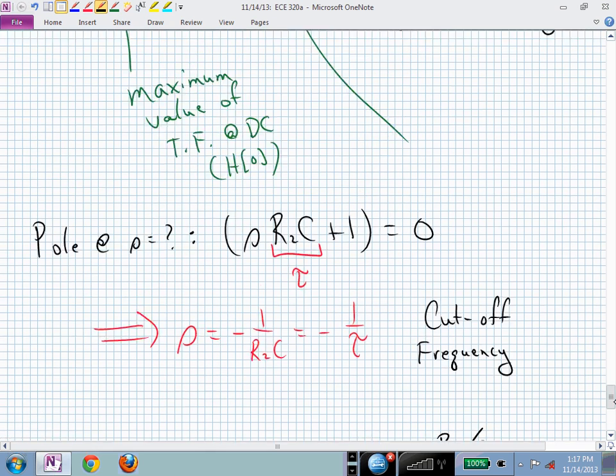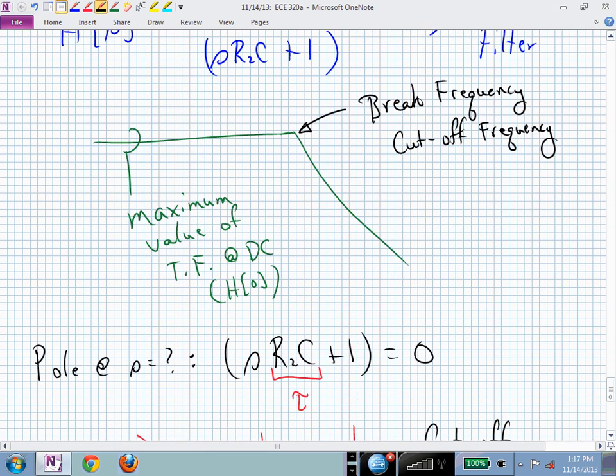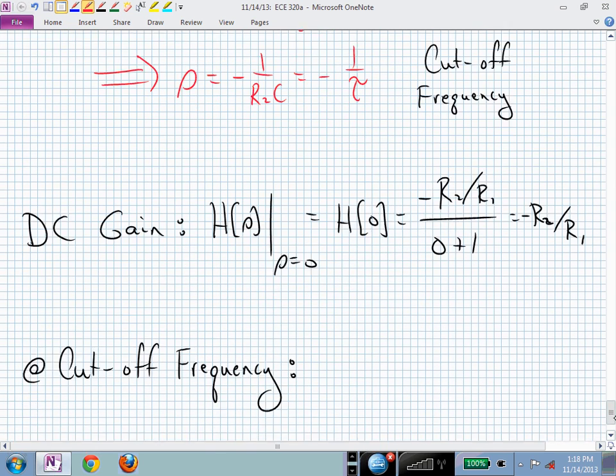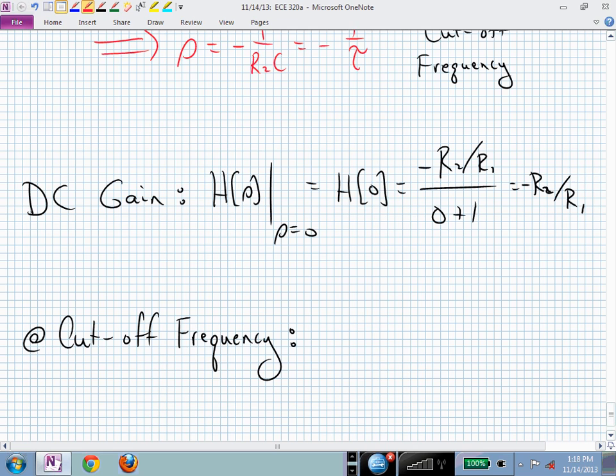In our Bode plot, we do straight line approximations, and it looks like it's the same, but theoretically, this curve is going to be down a certain amount at that cutoff frequency, and that's the 3 dB that it's down. Where does that come from? And that 3 dB in absolute terms is 1 over the square root of 2. So let's look at the gain of this